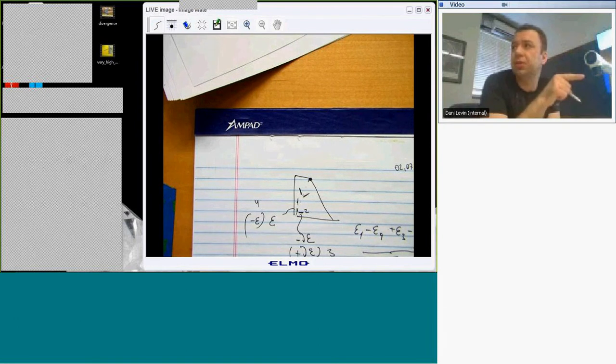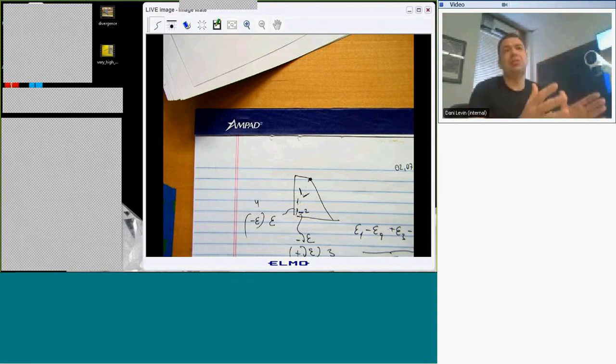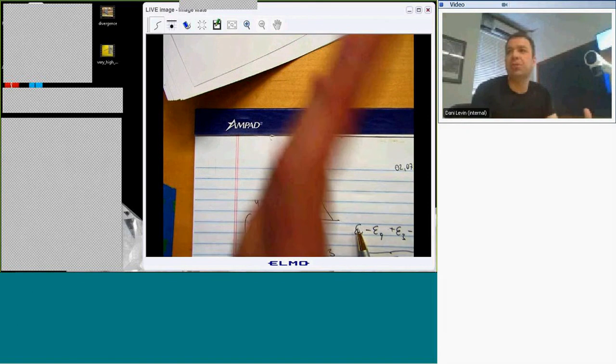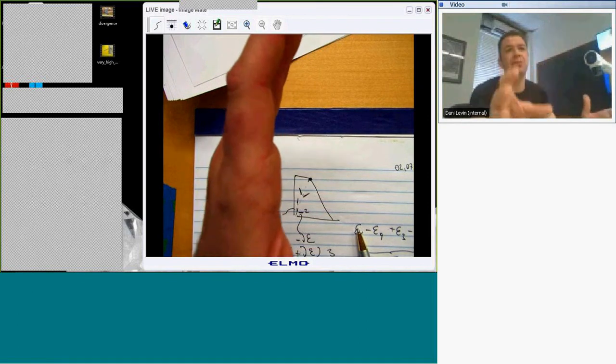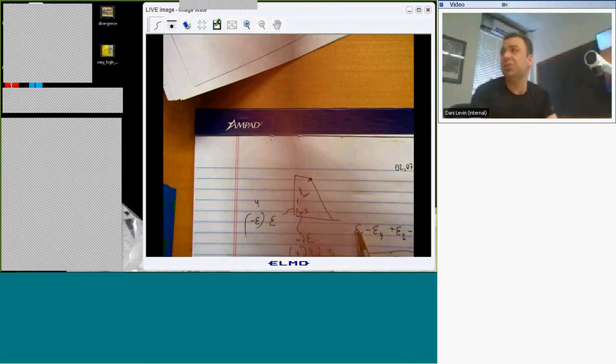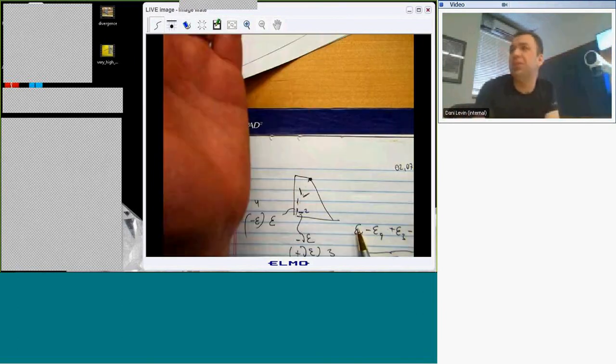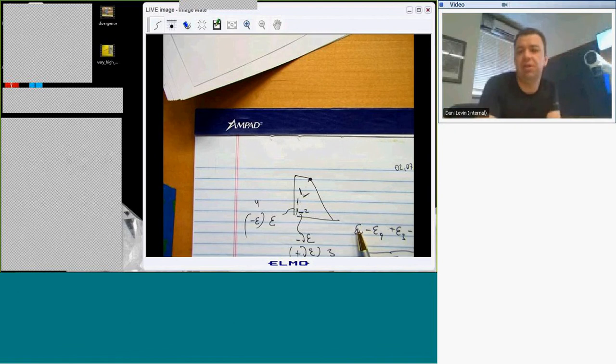non-contact displacement meter with laser beam. But you have to have it in order to use it. Yeah, but now that would be used in a wind tunnel test. Would you ever use something like that in a flight test? No, in flight test, the way that displacement meter works, you should mount it somewhere, and then it measures displacement related to this mount. In flight test, you cannot use it. So in flight test, it's usually only accelerometers and strain gauges.